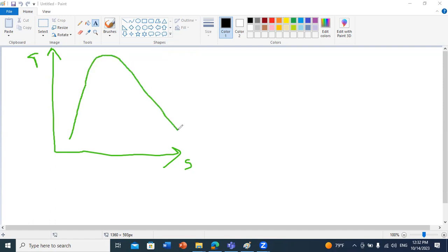So for point 1, this is the low pressure line, with a pressure of 100 kilopascal. And our inlet point is in the superheated region. So this is point 1, which corresponds to the compressor inlet.